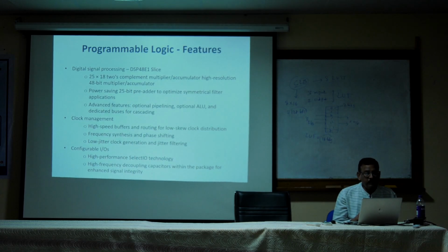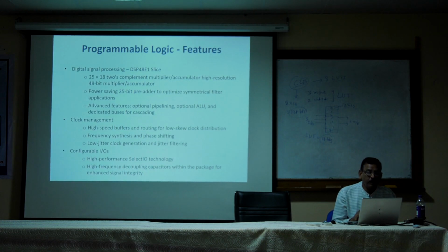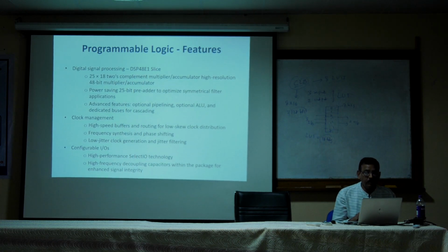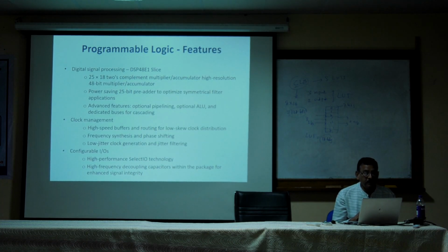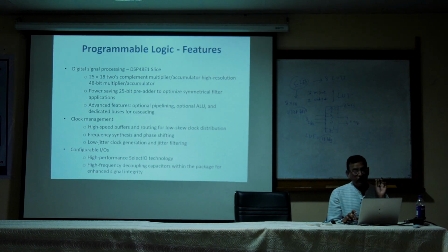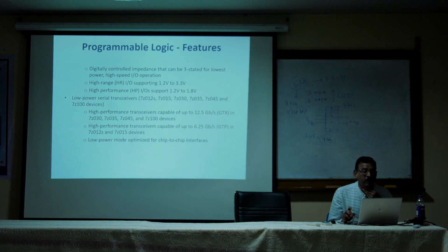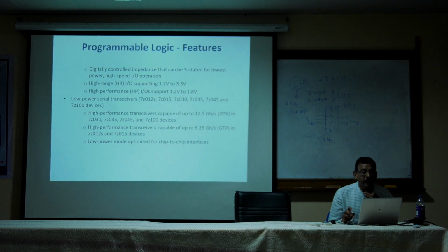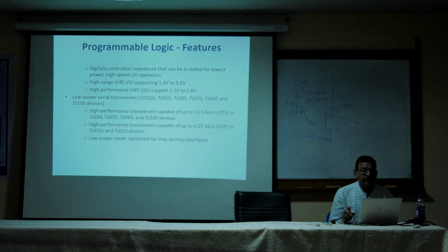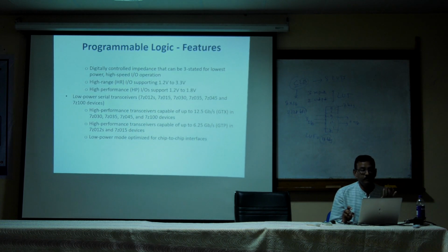Frequency synthesis and phase shifting, configurable IOs, input output pins, blocks, high performance SelectIO technology, high performance decoupling capacitors within the package for enhanced signal integrity. So, this is about IOs, input output pins, and a digitally controlled impedance that can be three stated for lowest power or high speed IO operation.